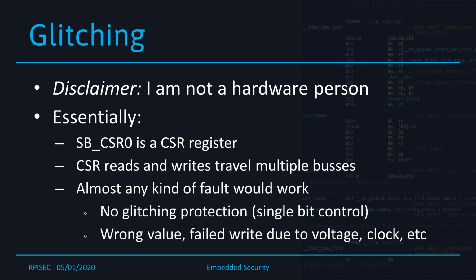So if it's a 0, it's unlocked, and if it's any value that is not 0, up to 8 bits or 16 bits or whatever you wanted, then you would be locking the boot ROM. And this means that even if you glitch the check or the write and it writes the wrong value, it still wrote a value that is not 0. So the glitch didn't actually work, and you don't get to recover the failed information.